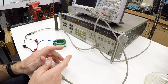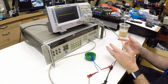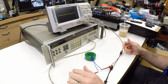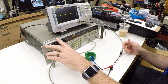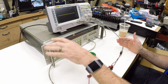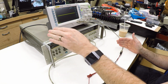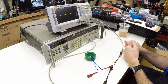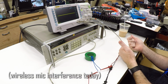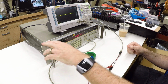But there is another way to visualize the frequency response, similar to the Bode plot that I showed in the last video, with an oscilloscope. And the way you do that is by using a sweep on the function generator to sweep through a range of frequencies, and then time the horizontal sweep on the oscilloscope to match that so you can see the frequency response across the frequencies. And I've been playing around with that. I thought it was kind of cool, so I thought I'd just do a quick follow-up video showing how that is done. So let me power up the function generator.